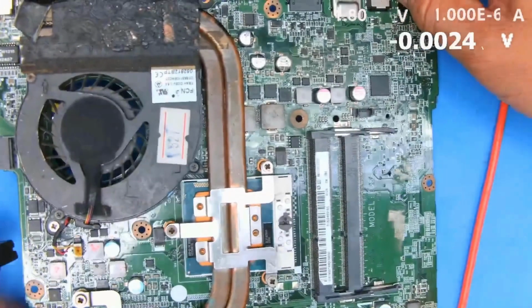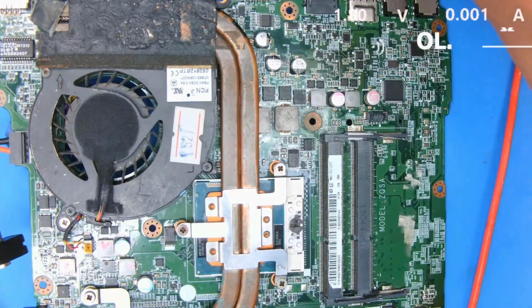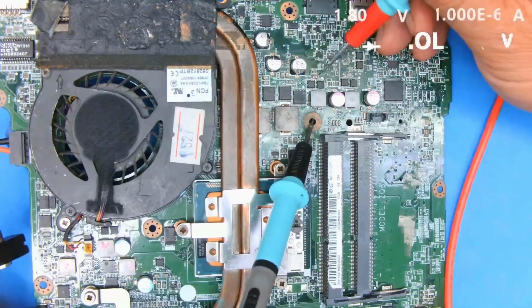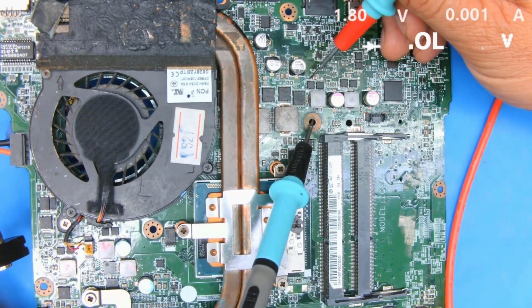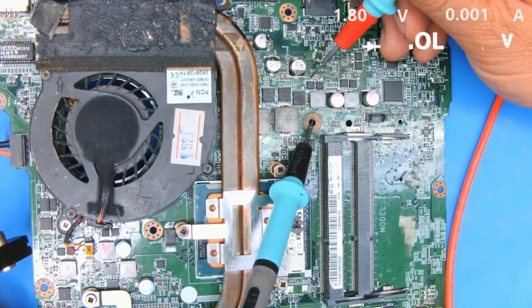Now, let us recheck or double-check here. The short circuit here should be gone now, right? Let me check with the meter first. Now, place the red probe on the ground. Double-check at the 49. See? The diode value has increased. Now it shows OL. See that? Normally this one is ground, which is 0. Now we've finished the repair.